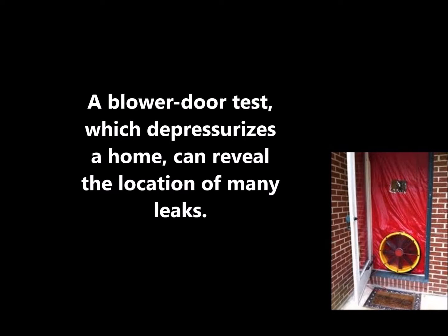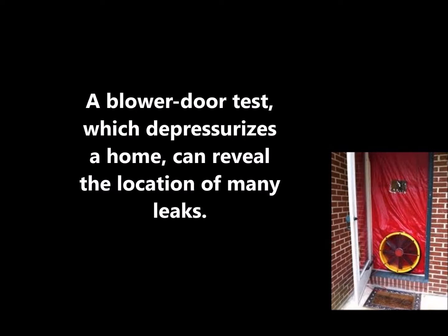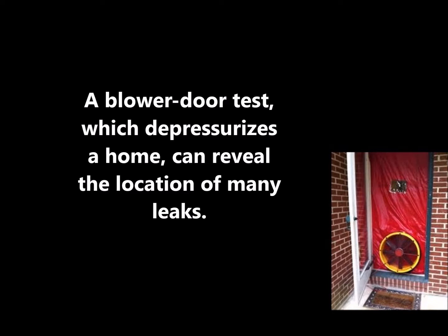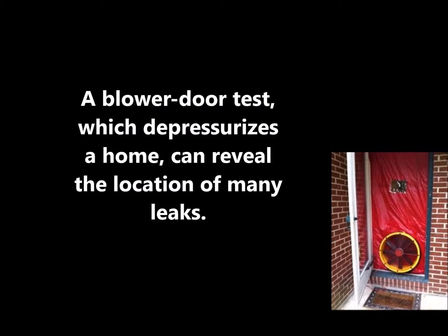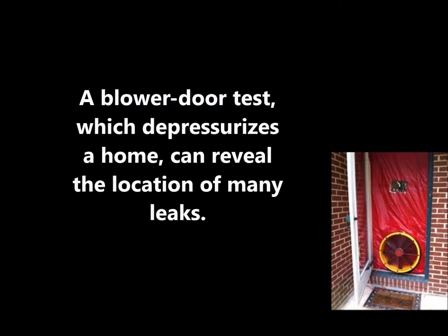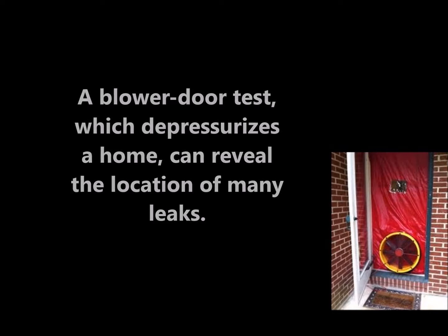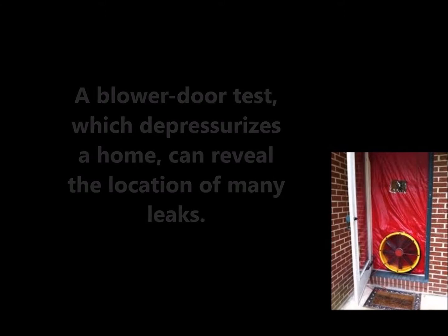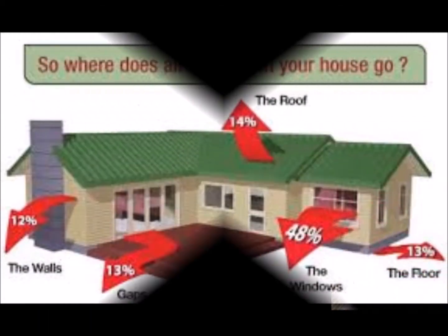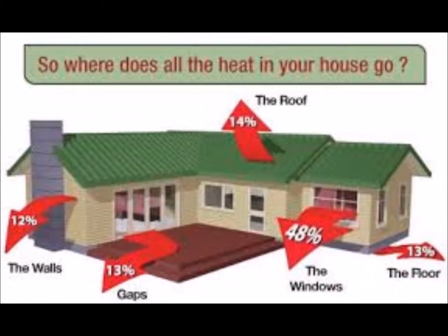First, look at the areas where different materials meet, such as between brick and wood siding, between the foundation walls, and between the siding and the chimney. Also inspect around the following areas for any cracks and gaps that could cause air leaks. The following areas also include parts of a house that would allow infiltration as well as exfiltration.